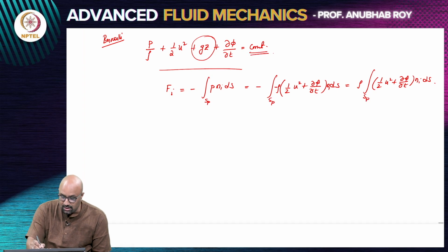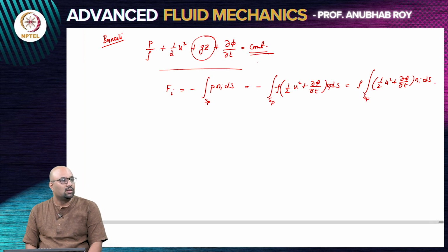Now, there is a constant here. Why did I not take in the constant? So, whatever is that constant pressure when integrated over a closed surface will integrate to 0. If you think of the constant being an atmospheric pressure or some constant value, if you integrate any constant pressure, normal force over a surface, it will be 0.